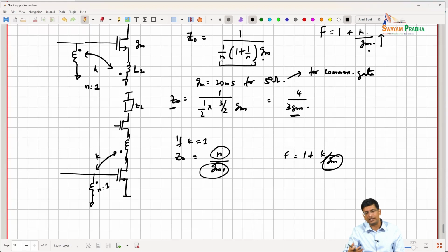So in all of these LNAs that are matched with 1 over gm, there's always this concept of gain boosting, where what we are trying to do is be input matched, but at the same time use a larger gm, because the input referred voltage noise is 4kT over gm. So I want to increase the gm, but I can't because the gm is constraining my matching.